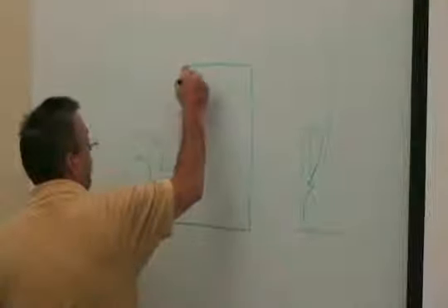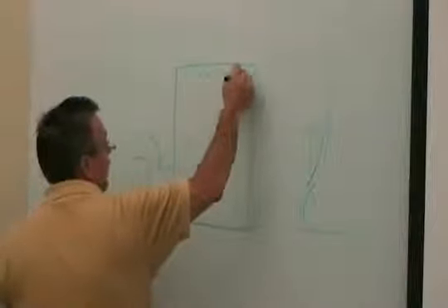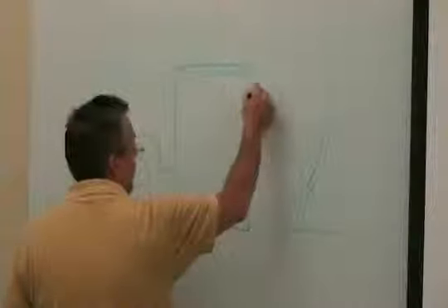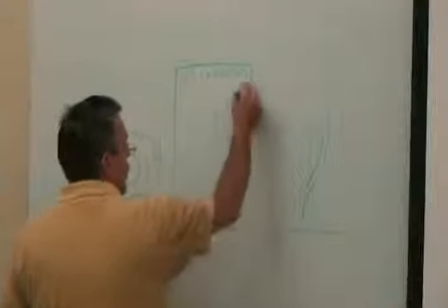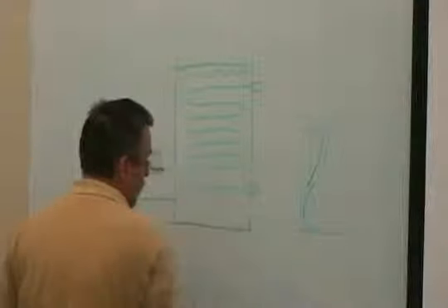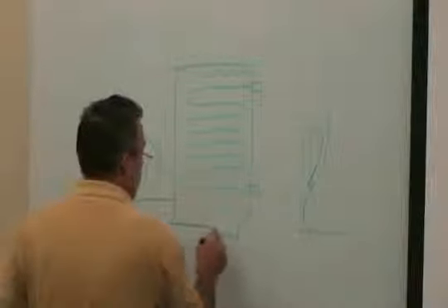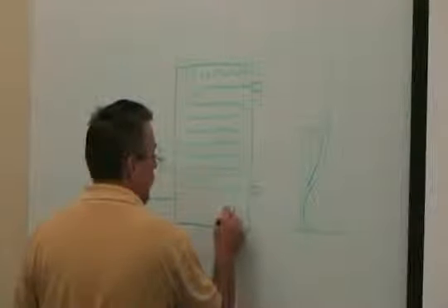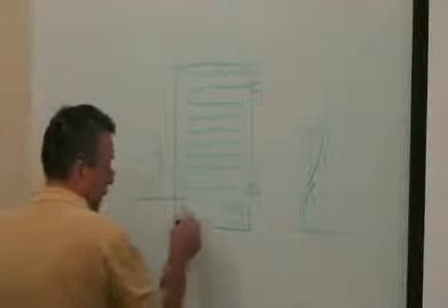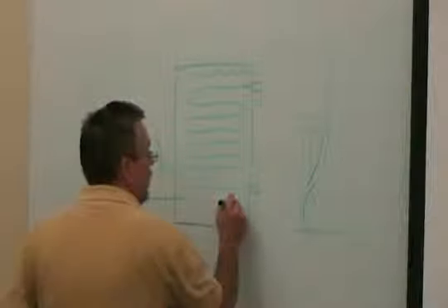They come in different versions. You'll sometimes have a discharge damper right here. You'll have a heat exchanger that comes in, a galvanized or copper heat exchanger. It fills up the whole box. Then you'll have a spray pump sitting in here, and you'll have a basin full of water. That basin full of water has got to be chemically treated to prevent biological growth. And this spray tree